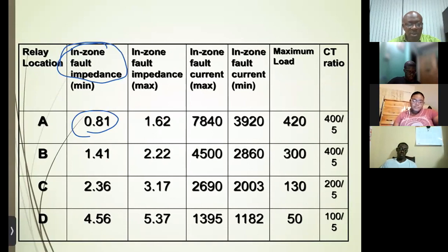So it's 11 squared over 150 MVA. And we get 0.8. It's not exactly 0.81, but I wasn't very keen on maintaining the standard as far as the decimal place is concerned. Okay. So we have maximum capacity, which is the 150.